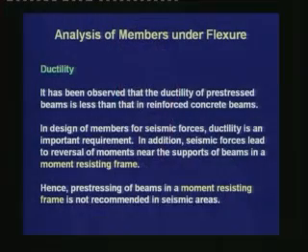It has been observed that the ductility of prestressed beams is less than in reinforced concrete beams. That means the ratio of phi u by phi y is less for a prestressed concrete beam compared to a reinforced concrete beam. In design of members for seismic forces, ductility is an important requirement. In addition, seismic forces lead to reversal of moments near the supports of beams in a moment resisting frame. Hence, prestressing of beams in a moment resisting frame is not recommended in seismic areas.